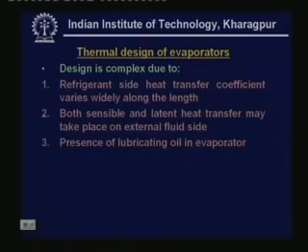Presence of lubricating oil in the evaporator. In a condenser, normally if the refrigerant is miscible with oil, then the presence of oil does not affect the heat transfer or pressure drop. But when you come to the evaporator, the oil tends to get separated from the evaporating refrigerant. That means once the liquid starts boiling, the lubricating oil gets separated from the refrigerant.